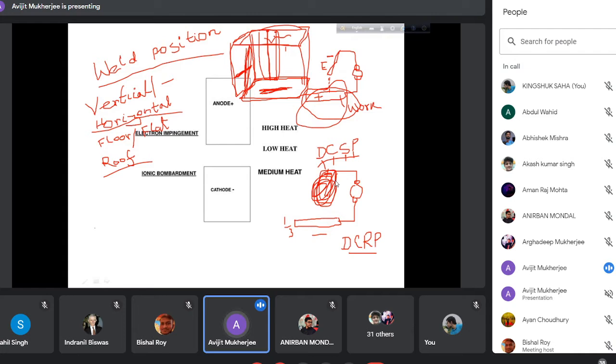So why I am telling this, in engineering application, say if you visit some fabricating shop or rail wagon manufacturing shop, you will find that when railway wagons, severe welding action is taking place. When roof welding is particularly conducted, they follow this procedure, tilting upside down to have a solid, sound weld.